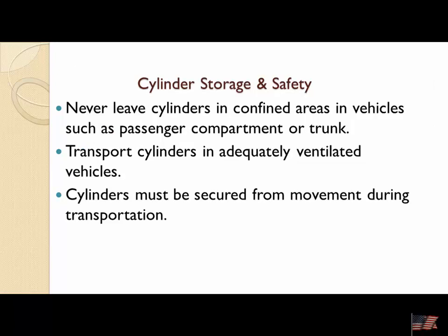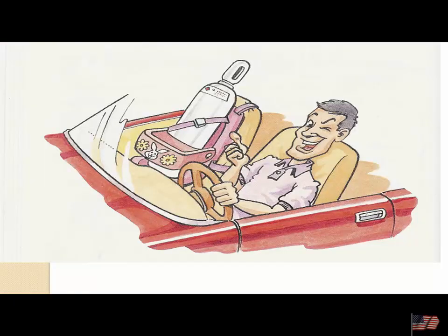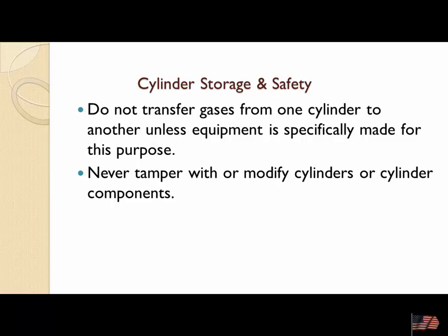Never leave cylinders in confined areas such as trunks. Transport cylinders with adequate ventilation, and they must be secured during transport. Yeah, I'm going to go ahead and put it into a child seat and seat belt it in, and we're good. No, I don't think so. Do not transfer gases from one cylinder to another, and never tamper or modify cylinders or cylinder components, and don't pull out your crescent wrench and go ahead and try to pull off the...